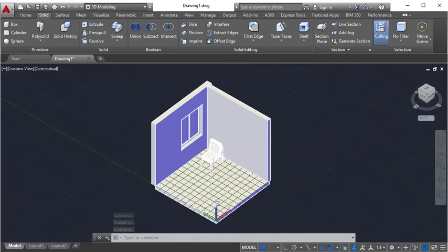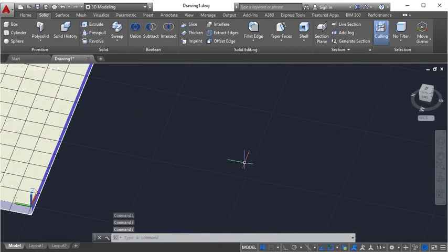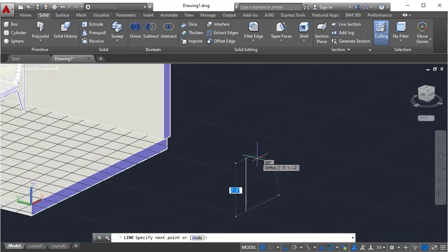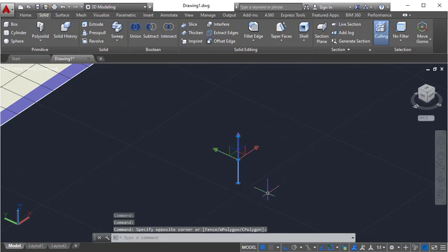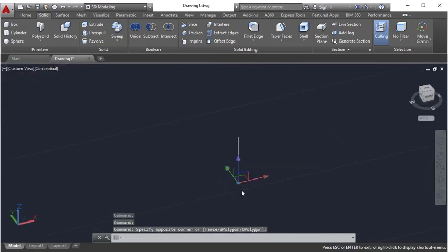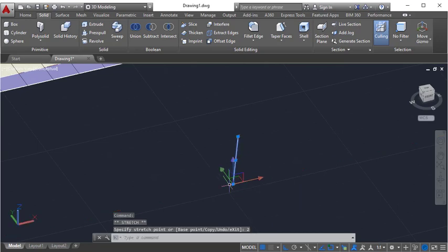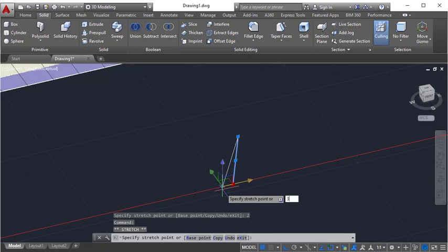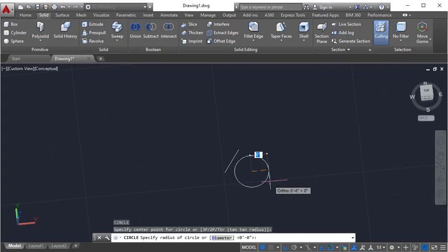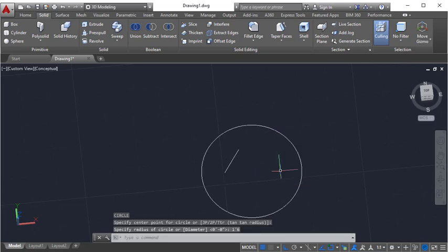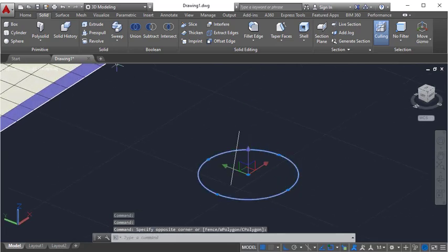So for the table also simple process, no need to worry about that. Like I will use line enter, switch on auto, height 1 feet 8 inches, and I can tilt it like 2 inches, no, of 3, total 5 inches. Now circle, if you use a circle, so if radius means 1 feet, like 1 feet 6 inches, like 3 feet diameter table.